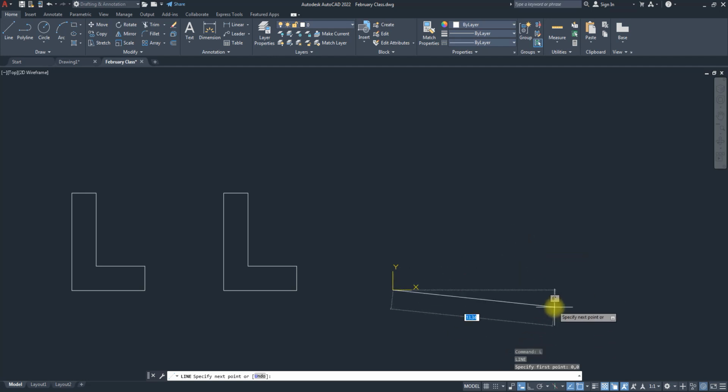The next one is what? Instead of saying at, I don't need to put at anymore because I'm using dynamic input. Dynamic input automatically adds at to it. So I just need to put the length, then the angle. Notice what is highlighting is the length. We know the length is 6. If I say 6, I have to hit tab for it to go to the angle. Then I put the angle 0. You're going to create it. The next line is 2 at 90. So type 2, tab 90, it goes up.